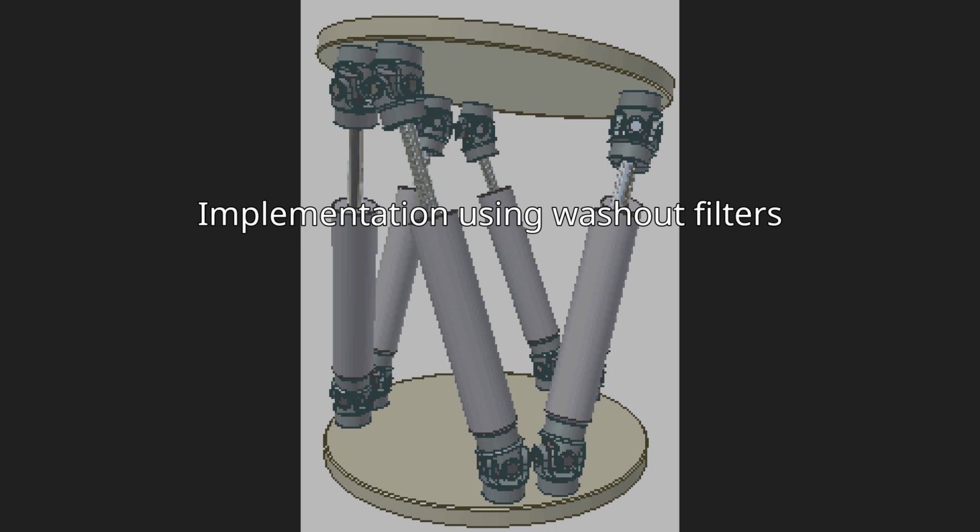For example, a pilot in a motion simulator may execute a steady, level turn for an extended period of time, which would require the system to stay at the associated bank angle, but a washout filter allows the system to slowly move back to an equilibrium position at a rate below the threshold which the pilot can detect. This allows the higher level dynamics of the computed vehicle to provide realistic cues for human perception, while remaining within the limitations of the simulator.